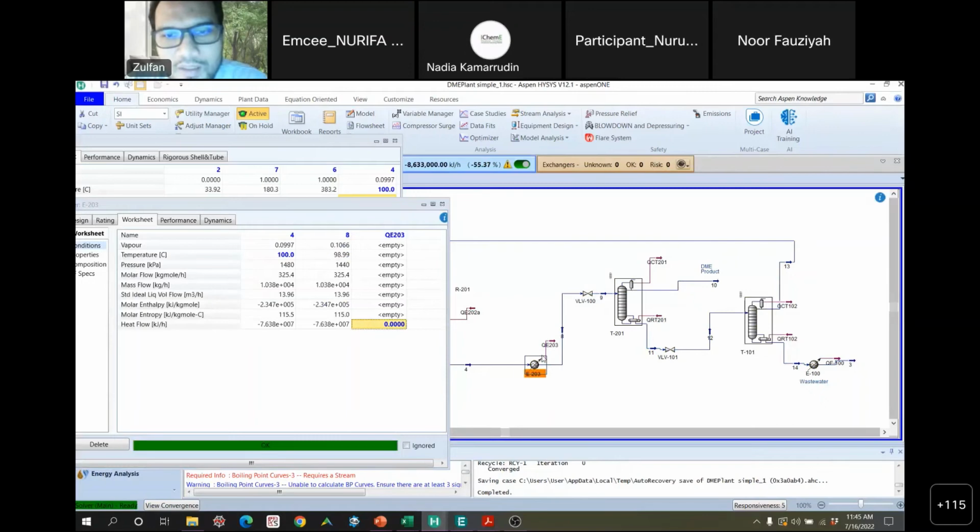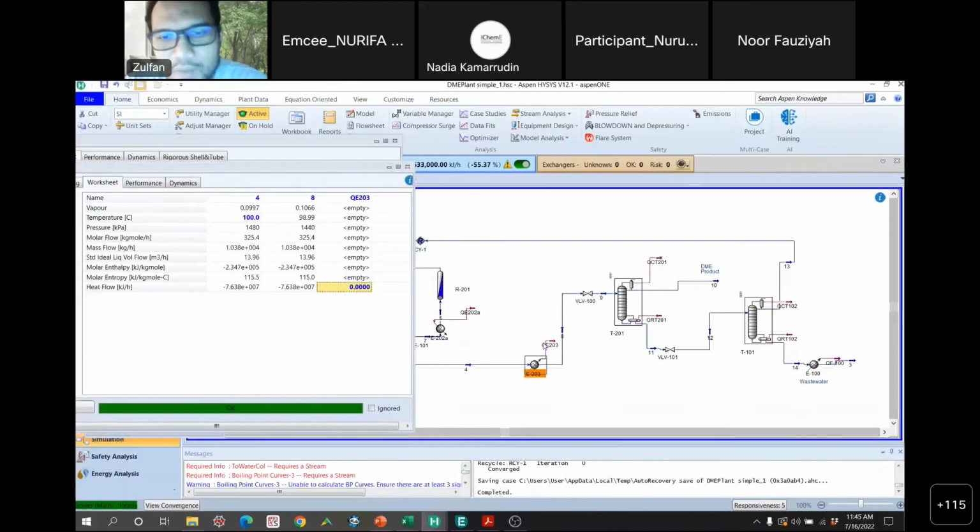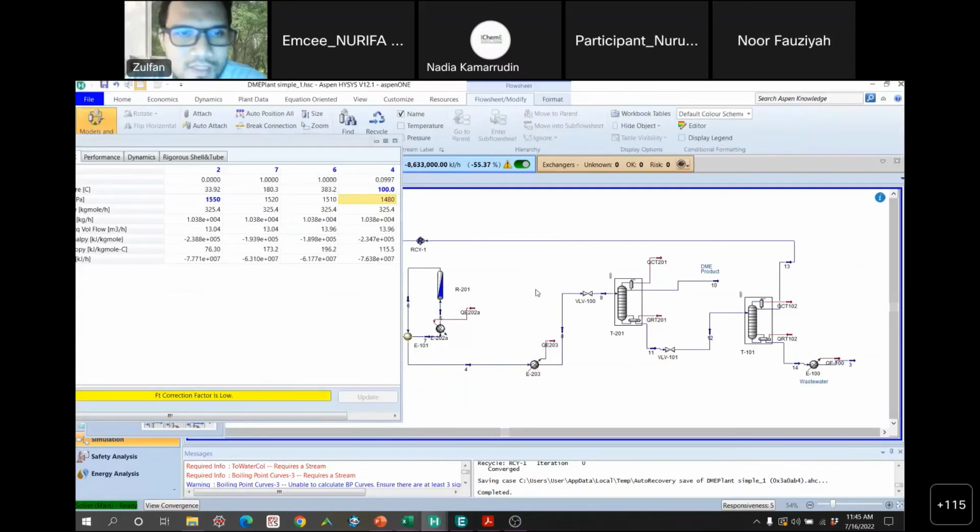Because if you make the mistake, like I did, of putting these options over there and forgetting to evaluate what is happening in this exchanger, and then you come to your boss and present the results in the mass balance, and your boss asks what the vapor fraction is over here and over there, and you say, well, according to the simulation the vapor fraction is increasing, then your boss will punch you in the face, because that is not possible, because this is a cooler, not a heater. Okay, so that's what it is.